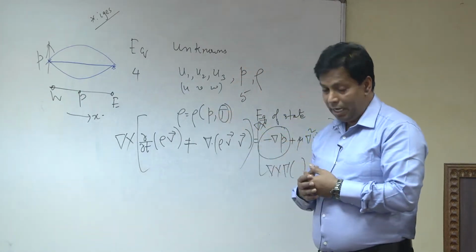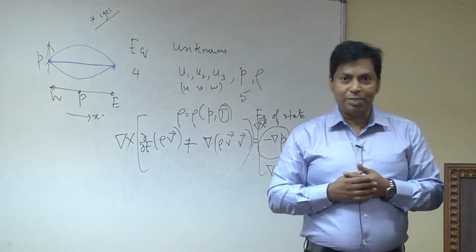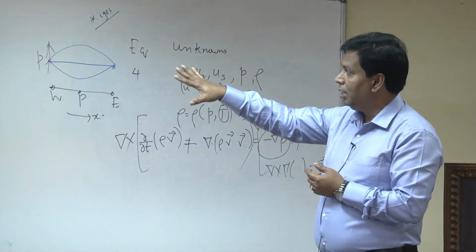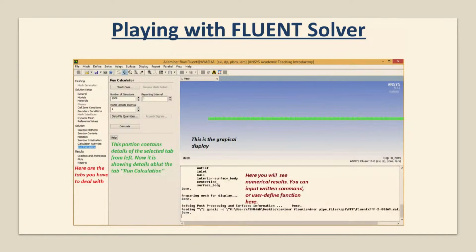Okay. So, this is Fluent. When you read a mesh file, it looks like this. The geometry shows the mesh here, and it will give all the information here, especially all the mesh information you can see from here. You have to check very carefully that the volume of the mesh is not negative. Sometimes if you have an error, it can give you a negative volume, so we have to check it. On the left panel you choose the solver and what kind of discretization to use, everything on the left side. So, you have to do it.